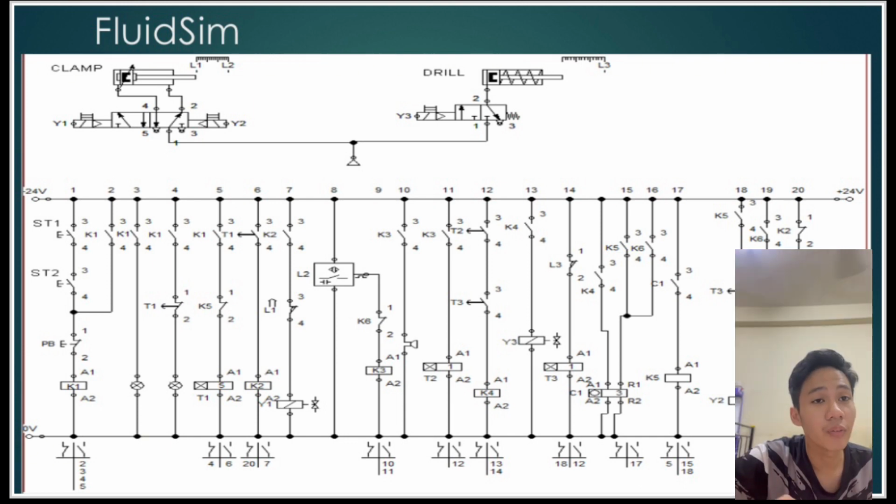After that, from line 12, you can see the relay K4 is triggered. So the limit switch for relay 4 is also closed, and the current will flow. As you can see, that is a counter relay, where when it is triggered 3 times, the function will be reversed.